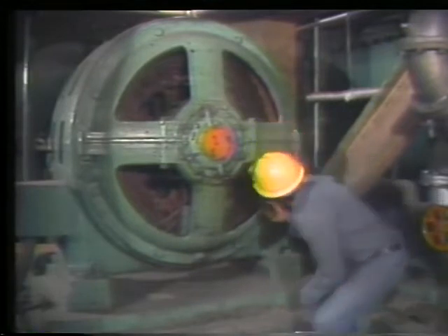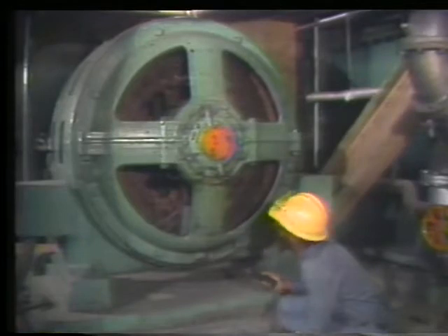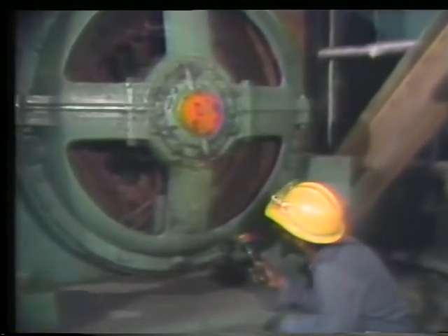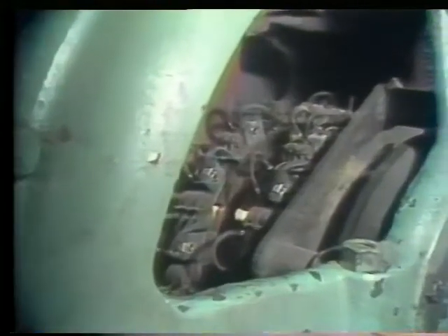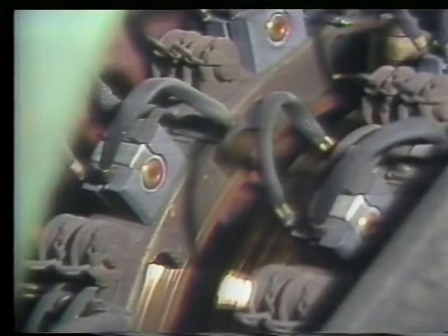Moisture can be a major problem for a motor, so whenever possible, check for dampness in and around the motor. Remember to check the bearing housing for signs of leaking grease or oil. On a wound rotor motor, examine the brushes, brush rigging, and slip rings. Be sure you notice the surface of those slip rings. If they're grooved or discolored, report their condition to your supervisor.